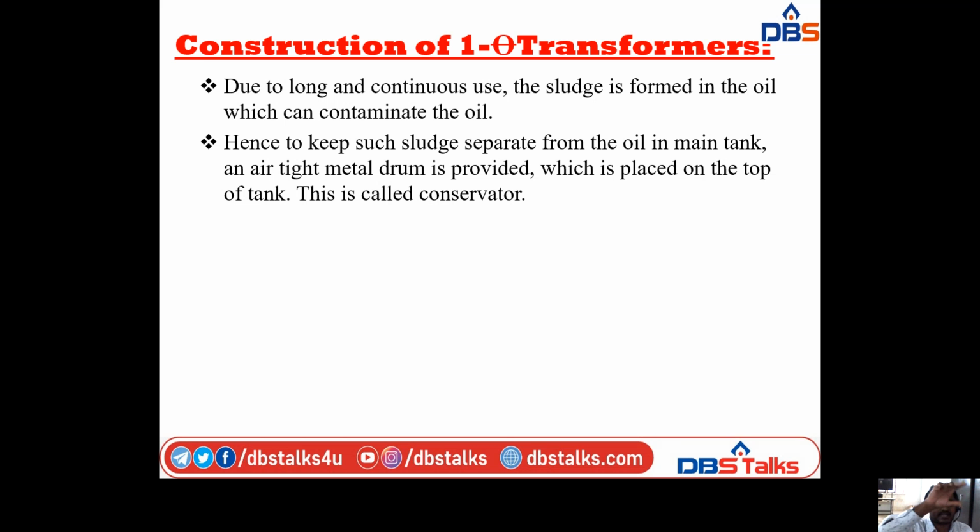That one is called the conservator. In the conservator, we separate the oil from the main tank, to overcome the sludge problem.